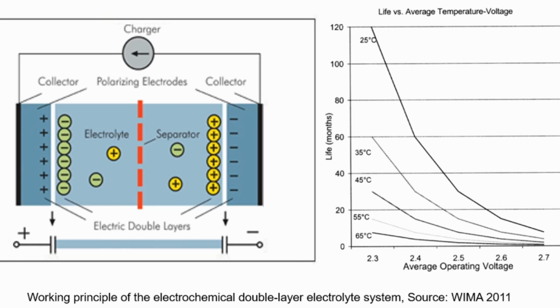So you see here this one. This is the electrolyte. This is the fixed electrode here, and this acts as a capacitor because here we have the negative, the electrons, and here we have positive charges, and here it's vice versa. So this is actually like two capacitors interconnected in series here. Here also you have a separator similar to the separator in the lithium-ion battery.